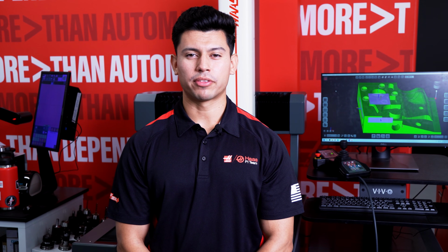The 3-2-1 method is widely used to constrain all 6 degrees of freedom in 3D space. It requires one feature with a minimum of 3 points to define a plane, restricting 3 degrees of freedom, a second feature with 2 points to define an axis, restricting 2 degrees of freedom, and a third feature with a single point, restricting the final degree of freedom.